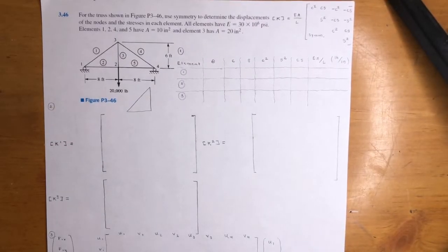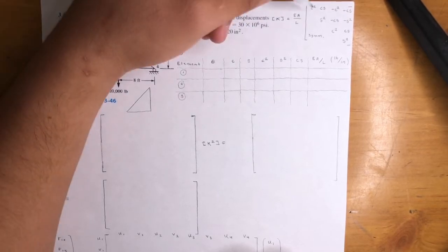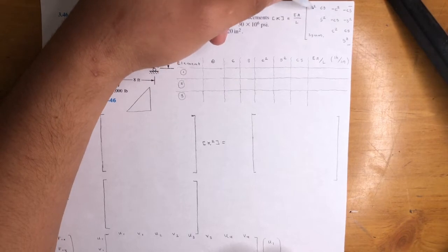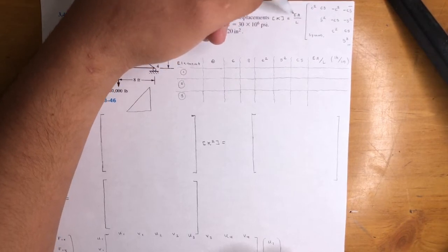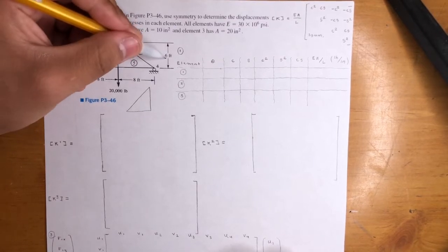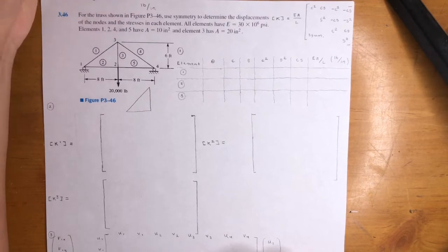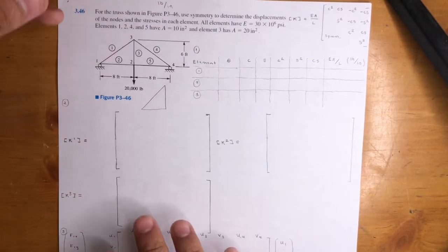All right, guys, so for these problems, we're going back to 2D. This is our stiffness matrix for a 2D problem in the X and Y direction. We have cosine values and sine values. We square them. We know E, A, L. Well, we should know L, right? They give us 6 feet, but we're trying to keep everything in pounds and inches, so we're going to have to convert this. Let's go ahead and do that right now.